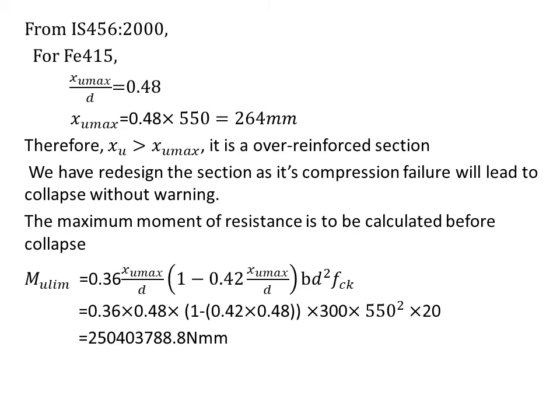There's a procedure for it. We already found the maximum moment, since they only asked about the maximum moment of resistance here. They didn't say so explicitly; we had to figure out that the maximum moment of resistance was to be calculated. It won't be mentioned in the question. When we check what type of section is used, and if they ask to find the moment of resistance, we have to find the moment of resistance before collapse, because it is exceeding that value that the collapse takes place.